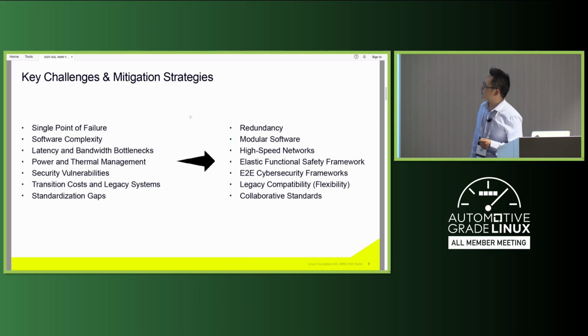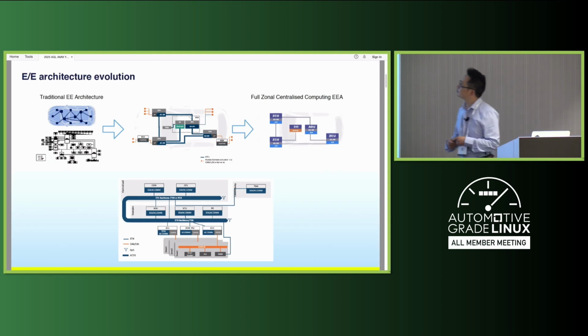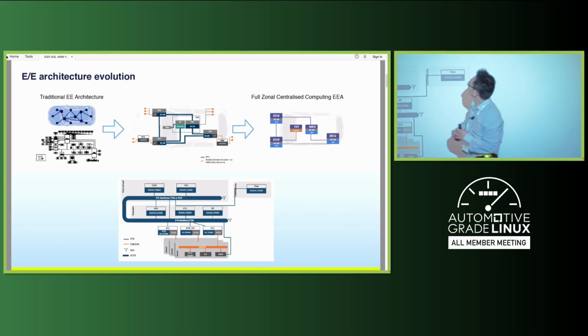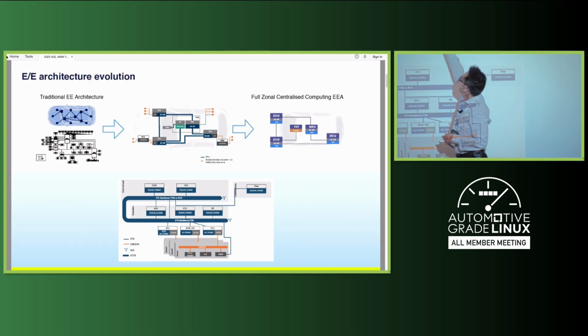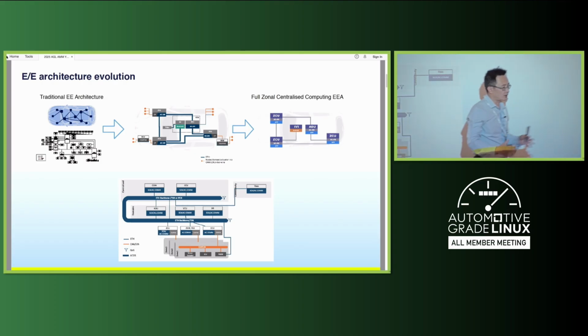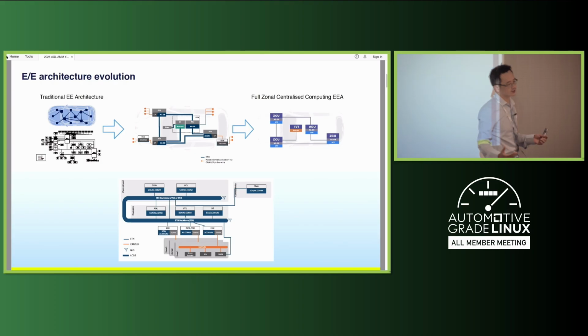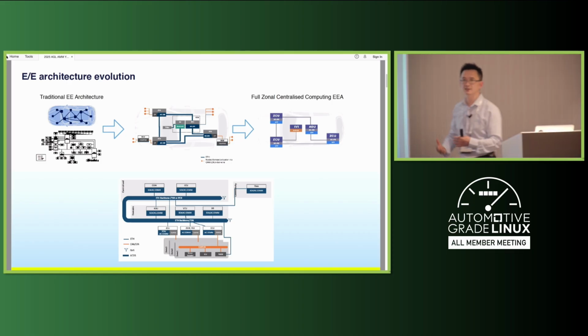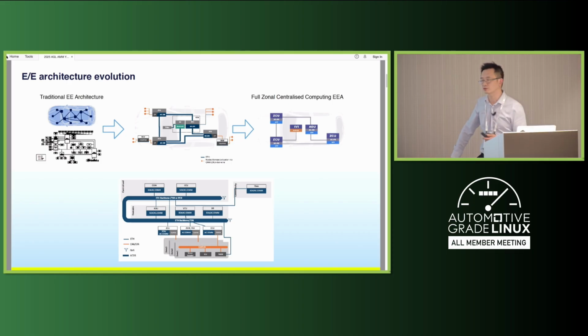Latency and bandwidth bottleneck. This is actually less intuitive, but if you look at the introduction of the zonal controller, because now you are connecting all the actuator sensors to the ZCU rather than all the way up to the domain controller.